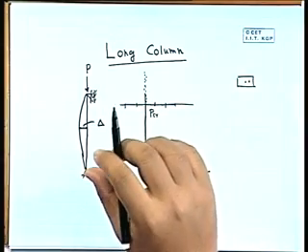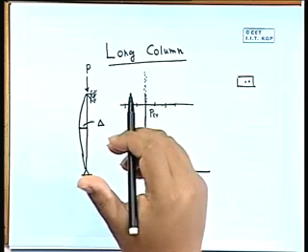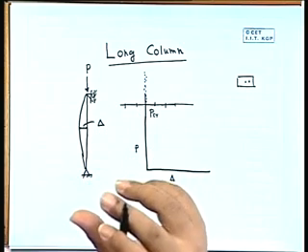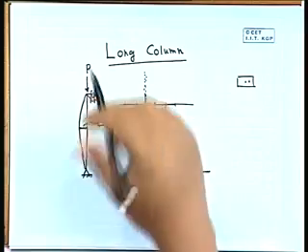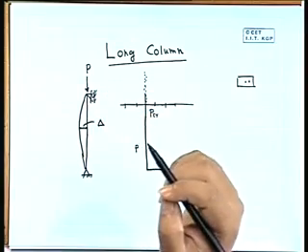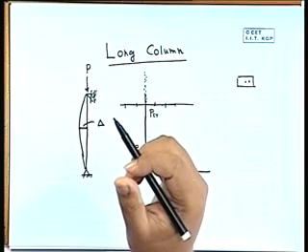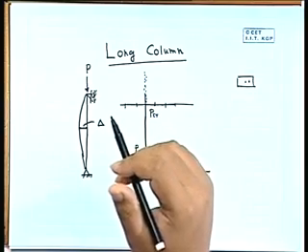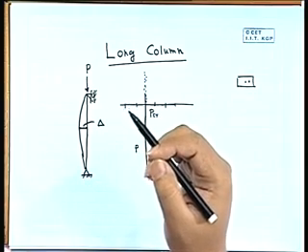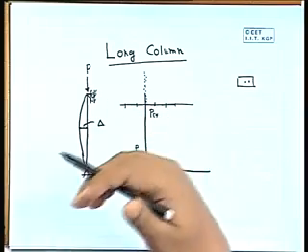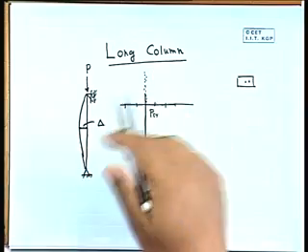This bending moment will try to bend that member, plus the axial load part is there. So, automatically from the beginning, if we apply a very small P, there will be a small moment, there will be small deflection. If we increase the load, our moment is basically P into e. So, when we increase the load, the moment part will increase, deformation will increase.